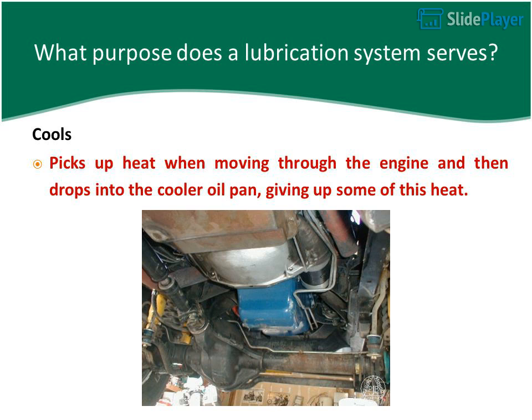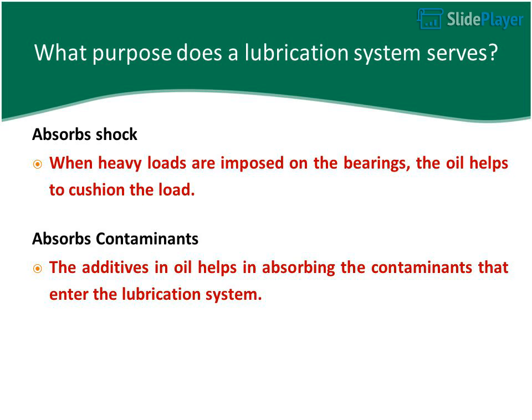Cools. Picks up heat when moving through the engine and then drops into the cooler oil pan, giving up some of this heat. Absorbs shock. When heavy loads are imposed on the bearings, the oil helps to cushion the load. Absorbs contaminants. The additives in oil help in absorbing the contaminants that enter the lubrication system.